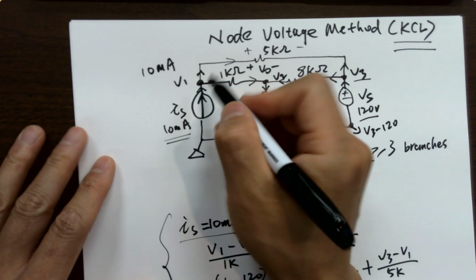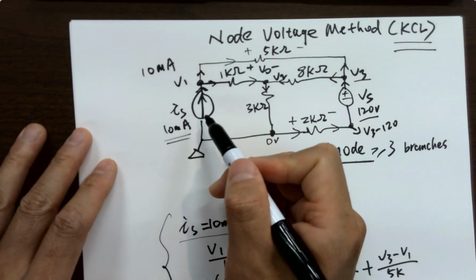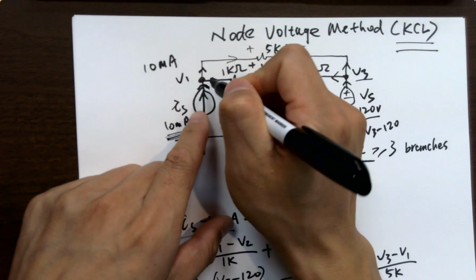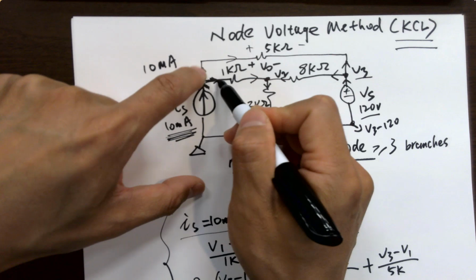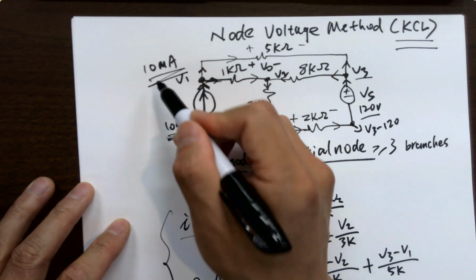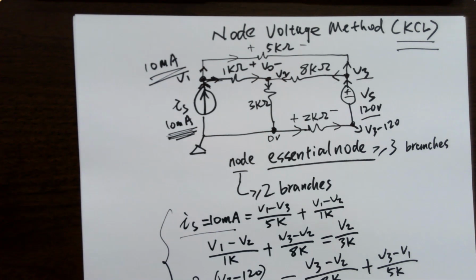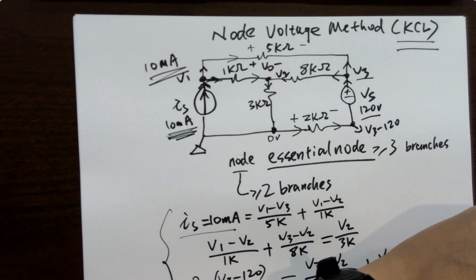The reason is this current source is given. It's 10 milliamps. We have to trust it. It's going to be 10 milliamps. Okay, so if this is 10 milliamps for sure, and you add the currents of these two together, they must be 10 milliamps, right? If you put a positive number there, you got a wrong answer. Just put a negative sign in front of it. Yeah.